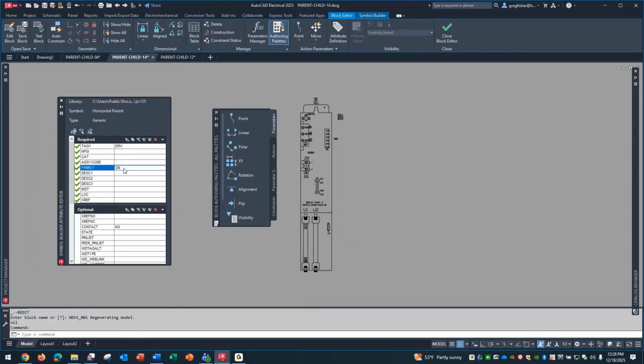So you want to make sure that you put the table from the catalog database in the family attribute field. And that's so important for those that don't know, because when you hit that lookup button to go assign it, you want it to look at the right table. And then the tag, you can make it anything you want.